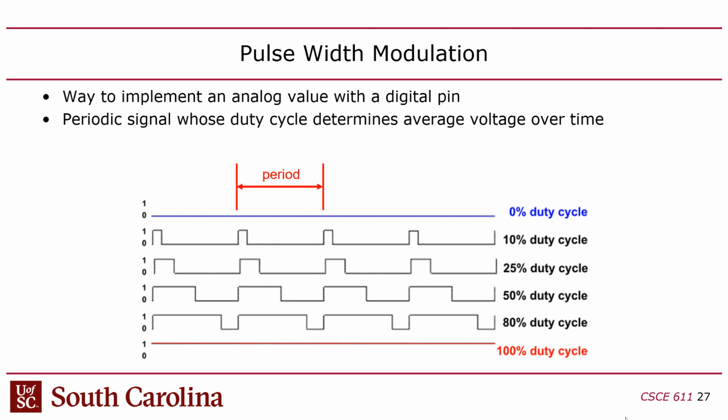But the speaker will still play the frequencies that are being modulated into this duty cycle over time, right? And that's why if you go to the grocery store and open up one of those greeting cards, it sounds a little weird, a little tinny. The sound quality isn't great, because I don't think those have the filter on the other side. I think they drive PWM directly into a speaker.